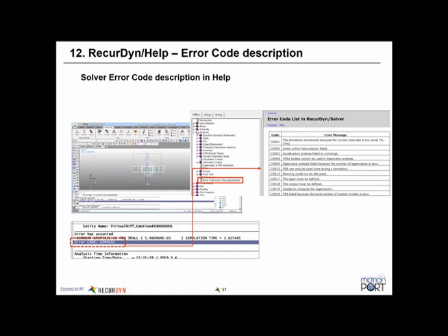In this case, we were monitoring contact penetration. We didn't know in advance what was a good contact value to use, and we didn't want to set it really stiff because then the simulation gets really long and may get some vibrational effects. So we usually try to relax the contact stiffness as much as possible, but clearly too much penetration is not acceptable.